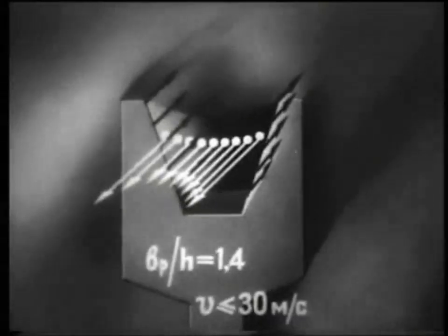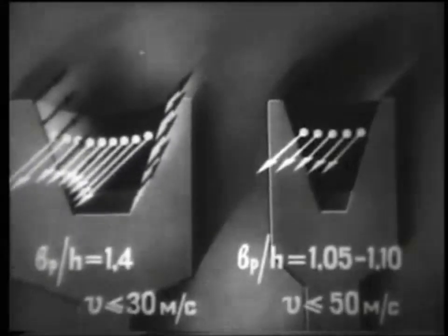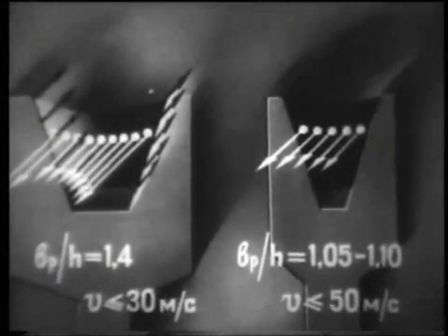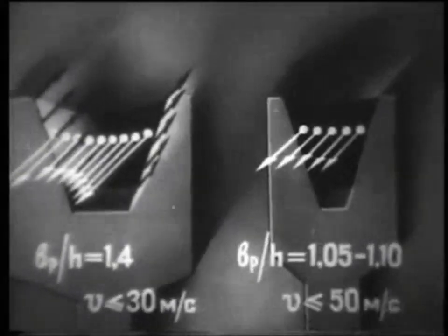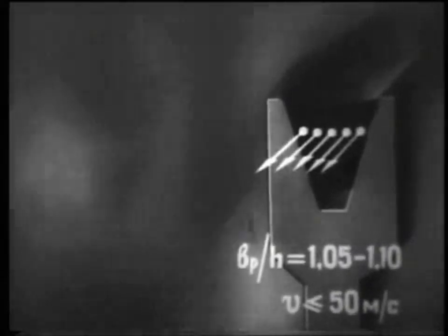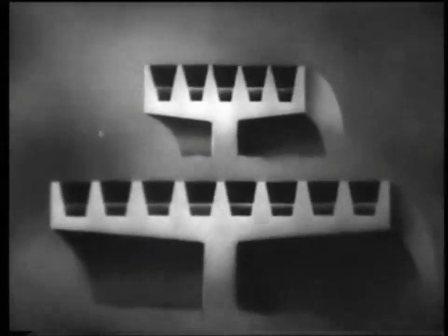The introduction of high-strength polyester cord made it possible to create narrow belts in which the load on the cord is distributed more evenly. Such a belt allows for greater speed. To transmit the same power, narrow belts require half as much width.